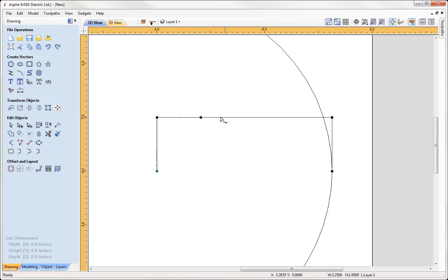This will make a little bit more sense when I come to create the actual curvature. Over on the leg here, I'm going to right click to insert a midpoint. That midpoint will be at 1/2 inch high, because we know that when we drew our cross section, we drew it so it goes up by 1 inch. And then I'm going to right click between this node here and this node here and insert a midpoint there, so I know we have a span that is 1/4 inch high, and we'll use that later on.